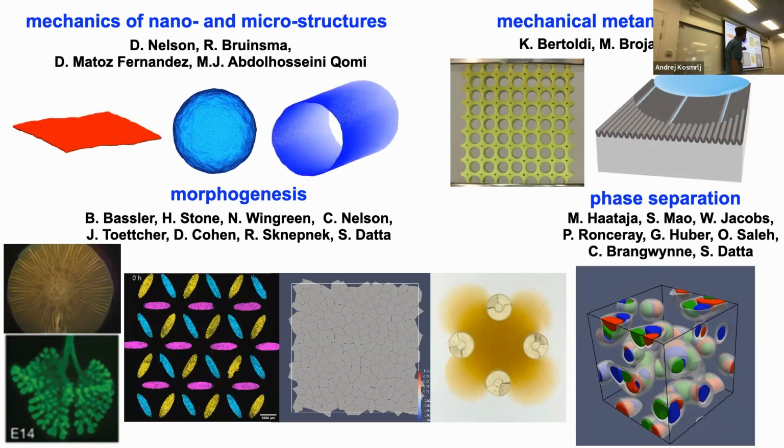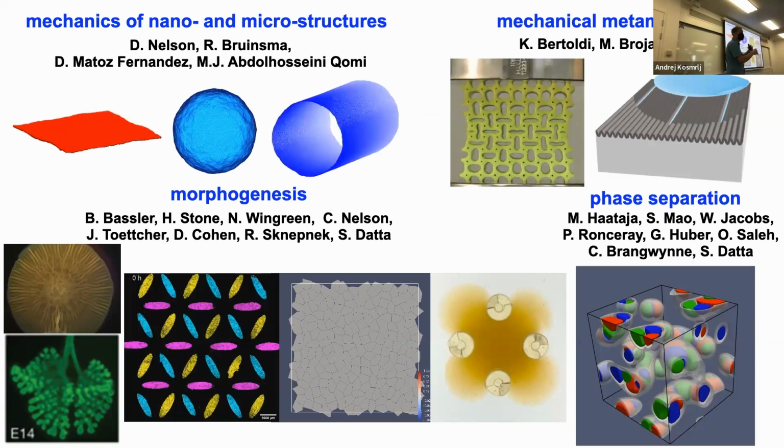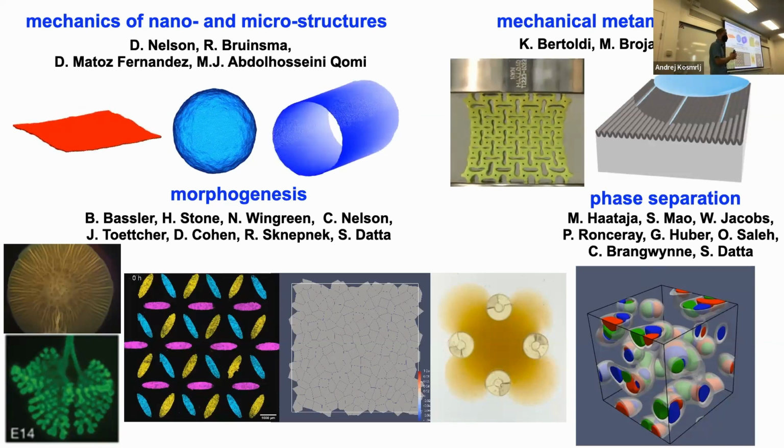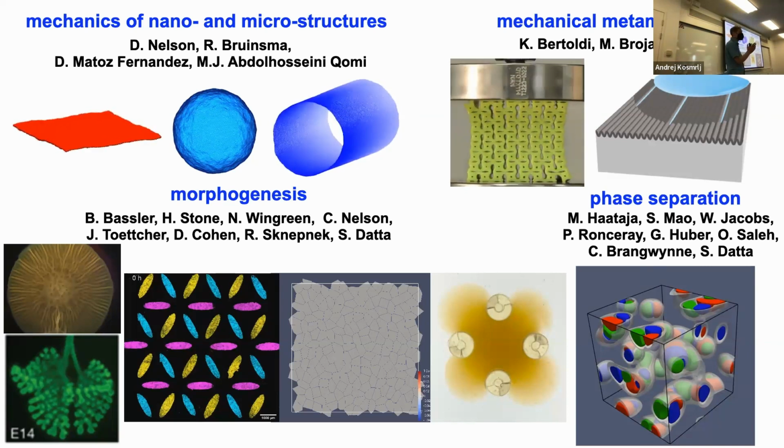But if you focus on this structure, once you compress it, you will see that once it buckles, it drastically changes the symmetries, right? Upon buckling, because you're going from one crystallographic group to another crystallographic group, this will change which degeneracies in the band diagrams are allowed or not. So we're basically exploiting these symmetry changes to try to mechanically tune these phononic band diagrams.